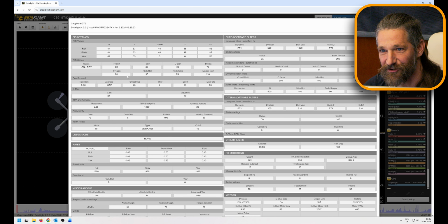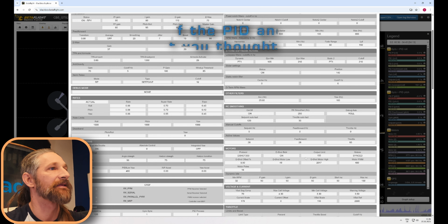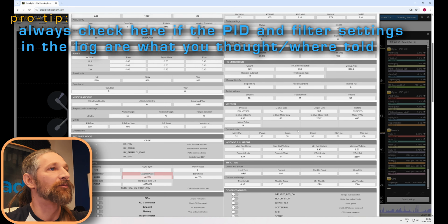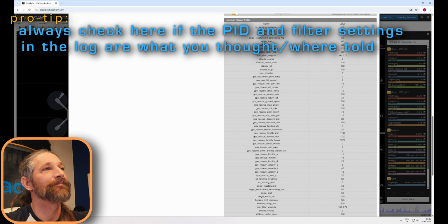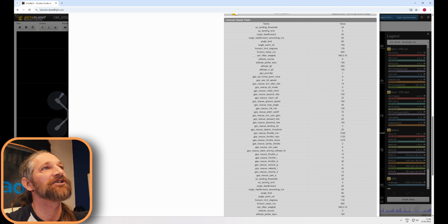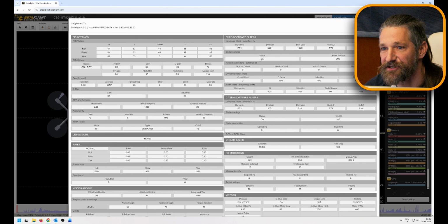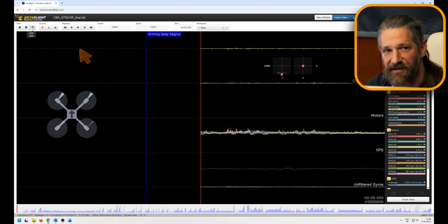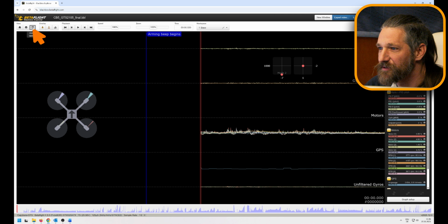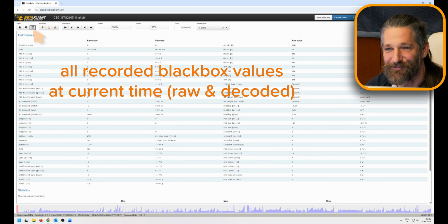It doesn't look like in the configurator, but you have your PID values, your sliders if you use them, general tuning settings, and your gyro and D-term filtering settings, as well as your rates, smoothing, and a bit more, especially CLI parameters might be of interest. You can close this by clicking beside it. You can watch this as a table.